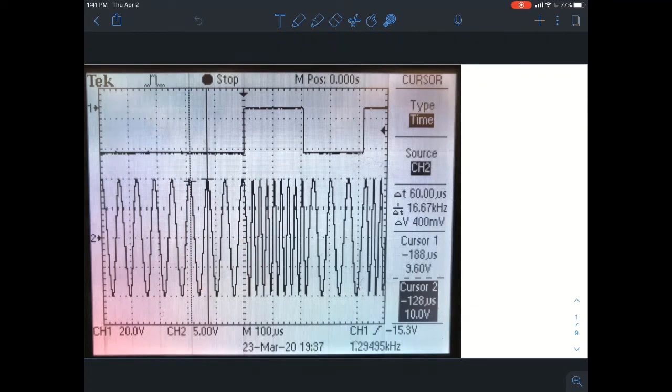What it asks us to do in the very first portion is measure the mark and space frequencies in the time domain. Using this display, you can see that I have marked out, using the cursor here and here, one cycle, so one period. The period is captured between those two cursors, so I'm going to put a box around it. They also give you the frequency, which gives you the information for the frequency of the space. So this is F sub space.